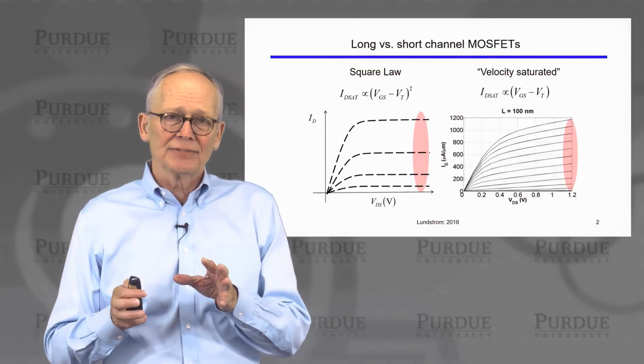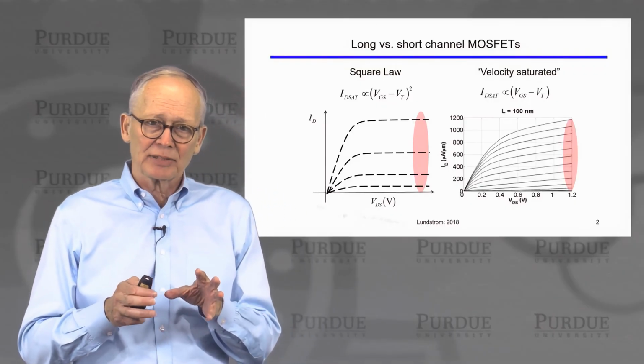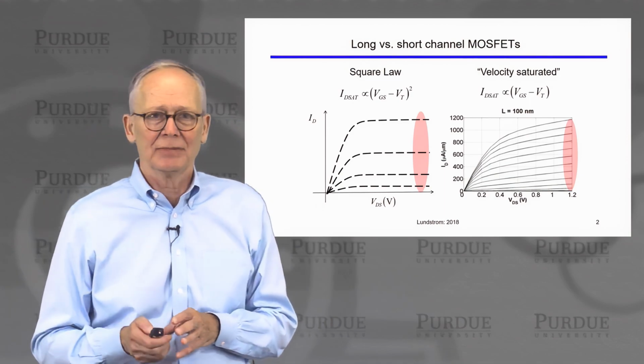So we'd like to derive a few simple equations that describe the IV characteristics of both long and short velocity saturated MOSFETs.